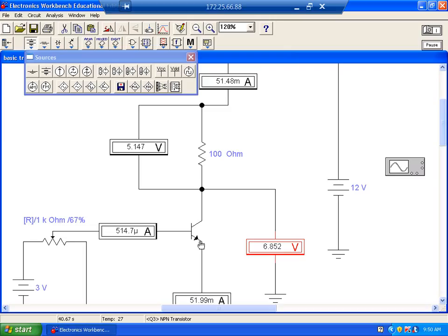So when we're dealing with operating the transistor between cutoff and saturation, we're concerned with how much voltage it can block when it's cut off, right? You understand? And we're looking at how much current it can conduct when it's saturated. When we're dealing with a transistor in the active region, we're concerned with how many watts we're making that thing dissipate. If you exceed the wattage rating on the transistor, then you could burn it up.